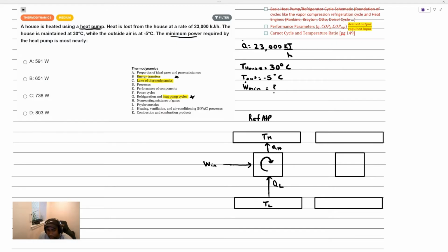We'll take that fluid that's now in a gaseous state and we'll input work into a compressor to compress it and heat it up. It'll be heated up so much that it's hotter than the outside, the surroundings, so we can achieve heat transfer with the outside of the refrigerator, right? The ambient temperature, because that gas will be so hot it can reject the heat to a high temperature sink. Now, refrigerators and heat pumps are very similar in their structure. They work exactly the same way.